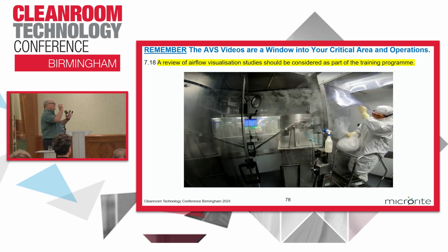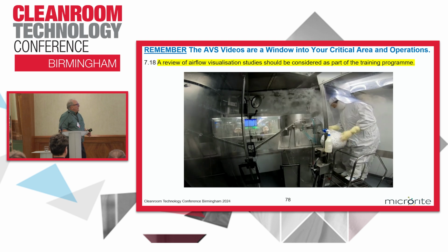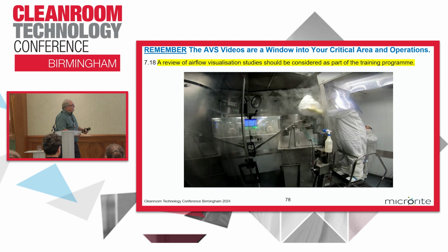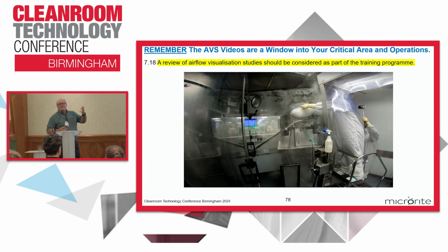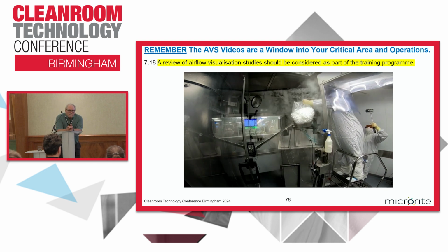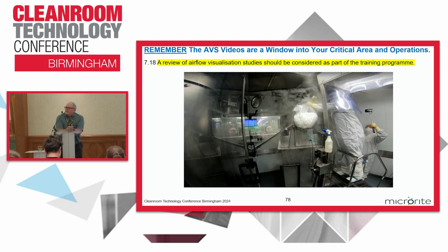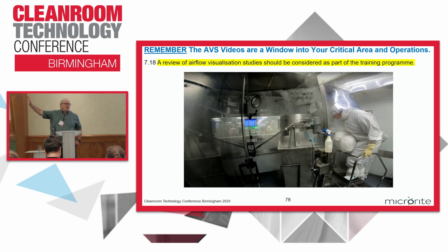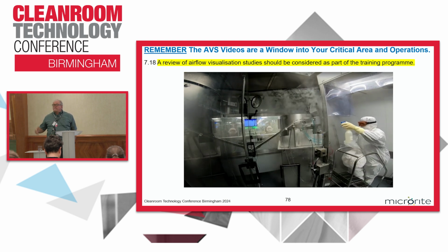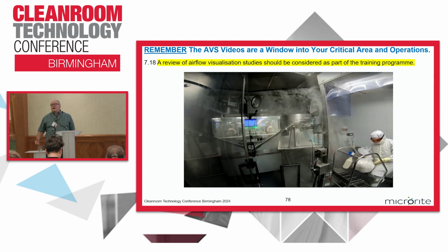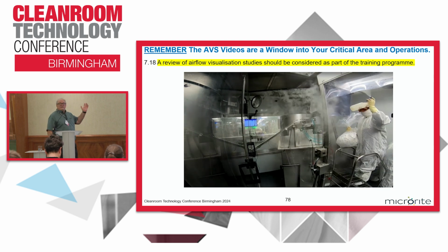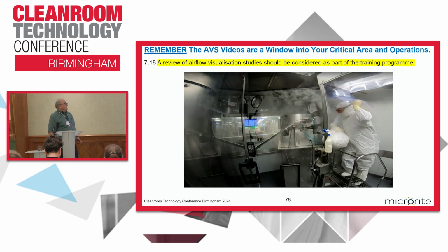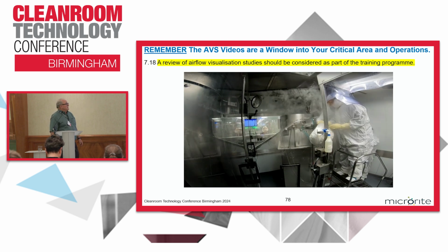He sprays before he goes in, and then he doesn't sanitize his hands at all. He's handling the step ladder, he's handling the bag, he's handling the curtains. One of the problems with cleanroom curtains is they're not treated like doors or walls. In aseptic operations, you're not supposed to touch the walls, right? You're not supposed to touch a door. If you touch a door, you sanitize your hands. The problem with curtains, people handle them all the time. You can't clean them very well. You can't sanitize them very well, and you need to understand it. His hand is dirty now, and so is his suit.